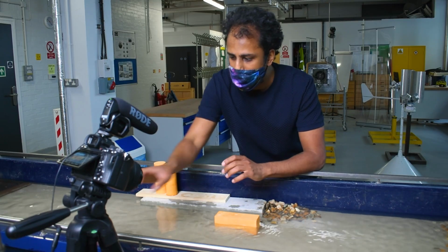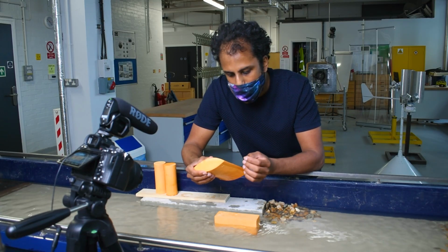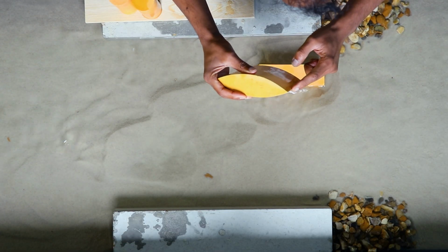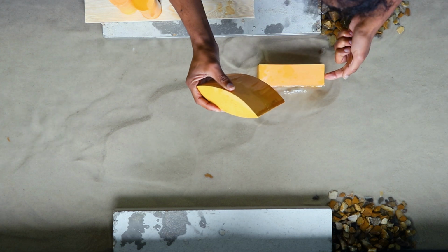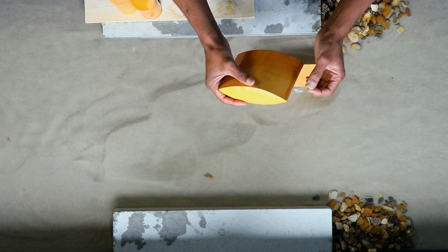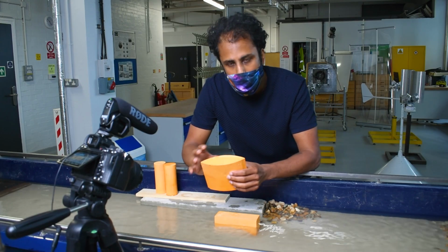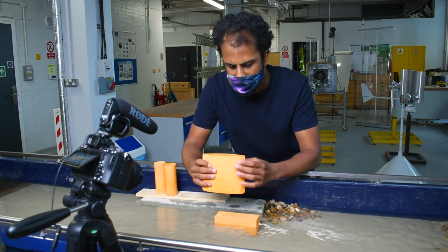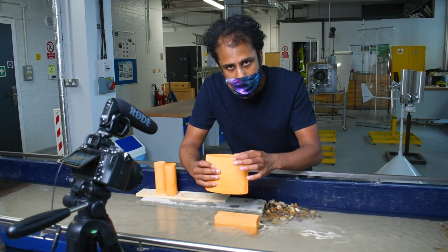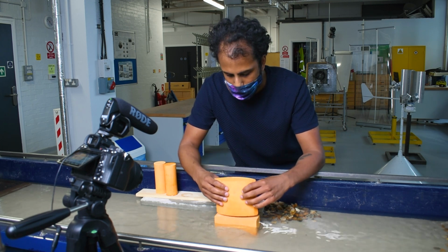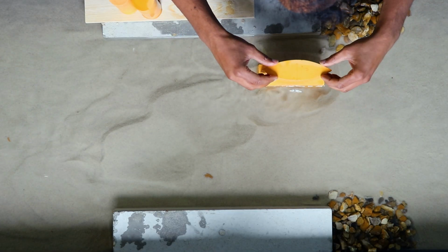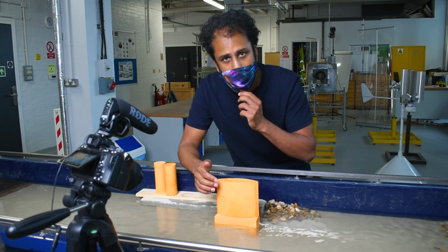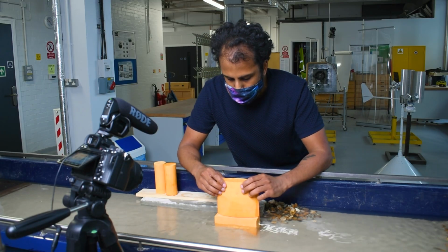And we design it like that because obviously this leading edge is a lot more streamlined, so there's less of a downflow able to form on that than there would be on this width here. And the acceleration of the flow of the boundary layer around the structure is much slower because it's a more streamlined, more gentle increase to its maximum width. Now its width is the same as this one, but it allows the flow to move past it without having to accelerate too much.